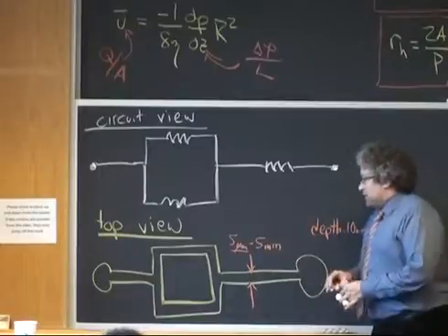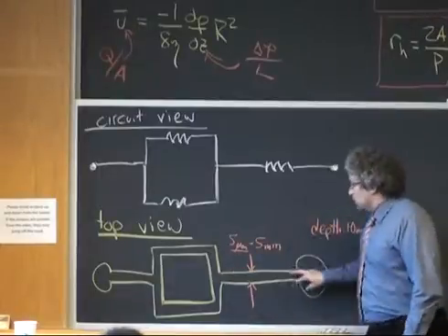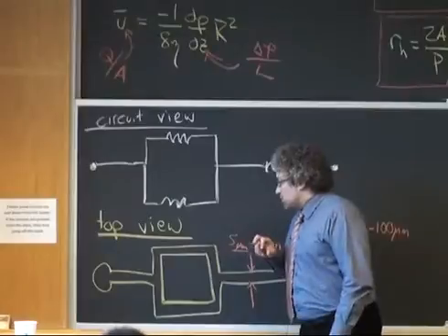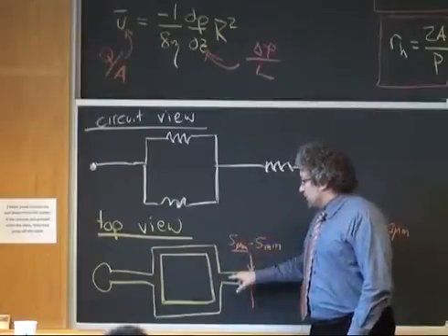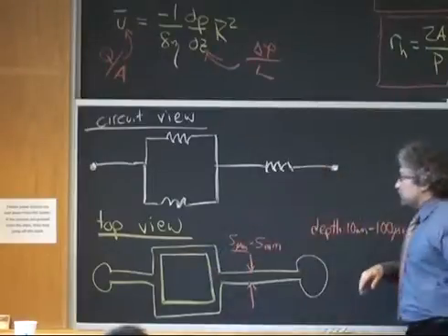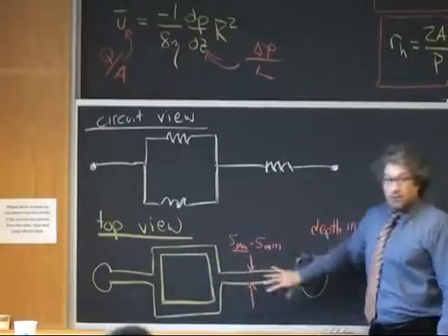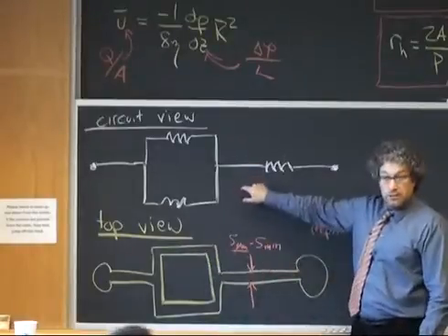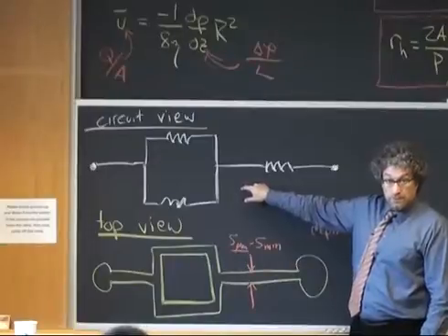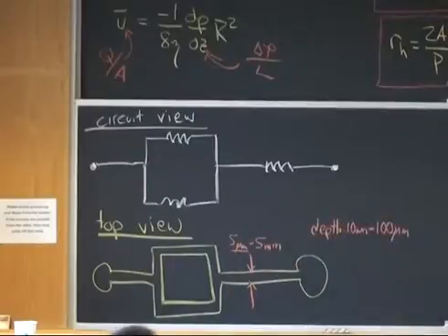When we have a device like this, we can think of all of these tubes as basically being hydraulic resistors. We can think of all the connections between the tubes as being nodes in an electrical circuit. And we can take a device that physically looks like this and recast it in terms of a circuit that looks like this. Again, recasting in the circuit allows us to take this linear relation, this Hagen-Poiseuille relation, and put that into a matrix form.